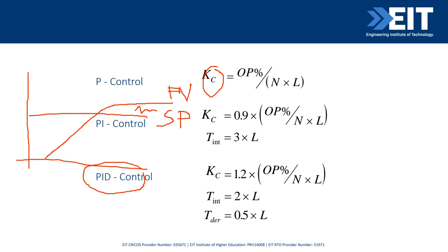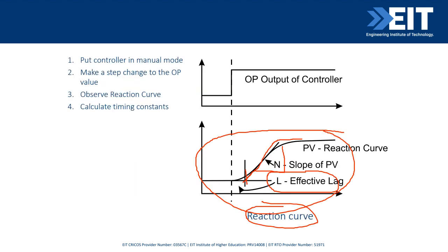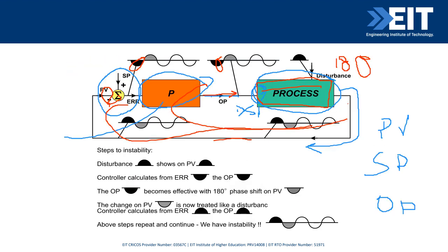I want to just reflect on this thing here. So here we've got the controller and the process. Now, when you have PI control in this, unfortunately integral adds a 90-degree phase shift. It's like a capacitor and an inductor. Unfortunately, it's a lagging phase shift like an inductor. So what you do is you add derivative control to actually cancel that I out.